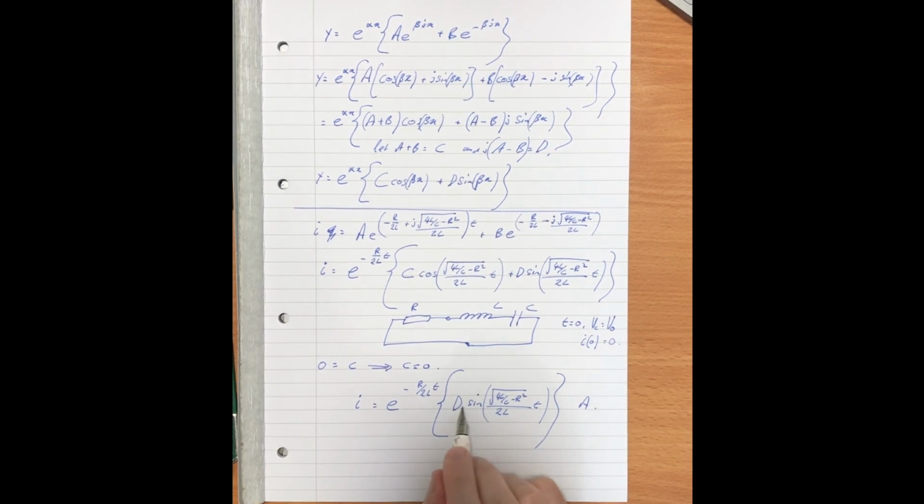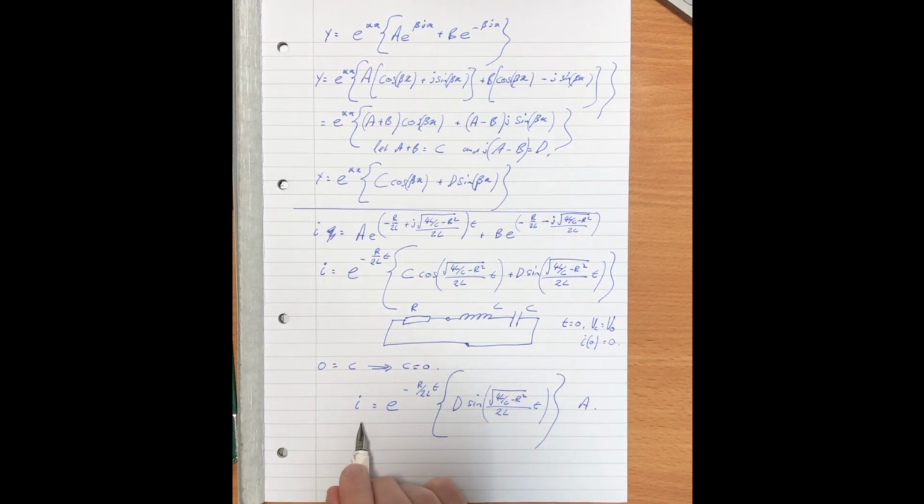Now, how do we find the coefficient D of the argument of sine over here? So we said before a few things. We said that for a capacitor, the current is going to be the same because it's a series circuit. So we can say i equals C dVc by dt. And we can also say that the voltage on the inductor, what we said before, equals L di by dt.